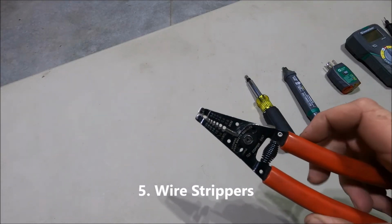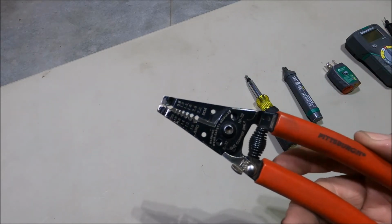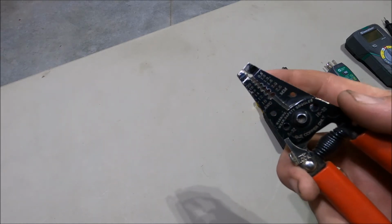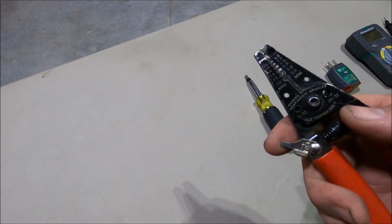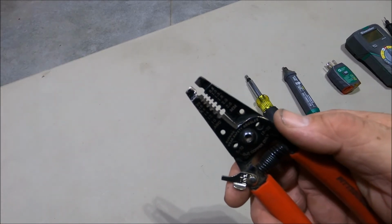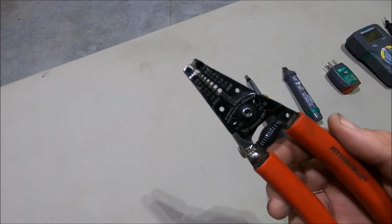Wire strippers. Invest in a good pair of wire strippers. I don't, because I'm cheap. But if you're going to be doing a lot of work, definitely invest in some good wire strippers, because you don't want to be cutting the wires while stripping them, especially if it's stranded wire. You want to make sure they strip the wire properly, because with stranded wire you can cut off some of the strands and make the wire actually smaller. So you want to make sure you get a good set of these.